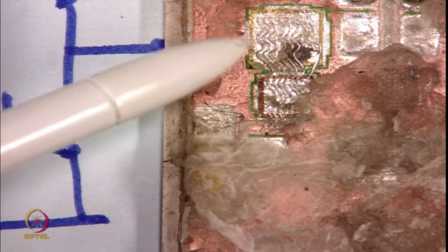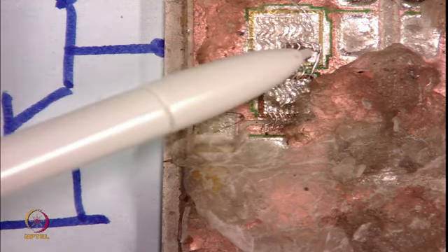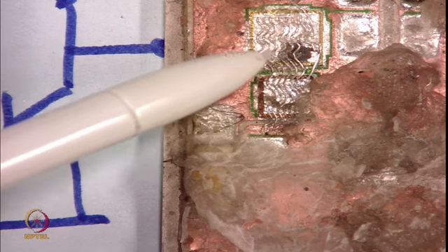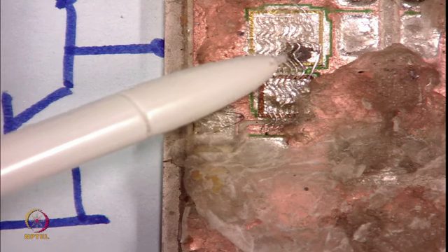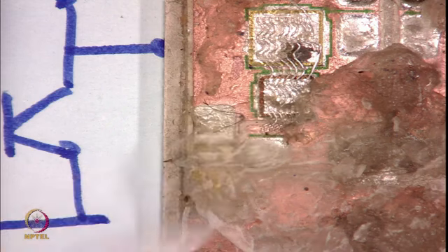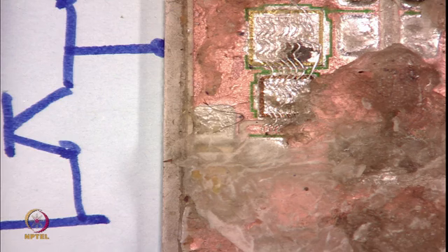You can see the bond wires. Some of these bond wires have been lifted, as you can see here. There is a black spot; probably this black spot is one of the reasons that this device failed. There was most likely a local thermal hot spot.